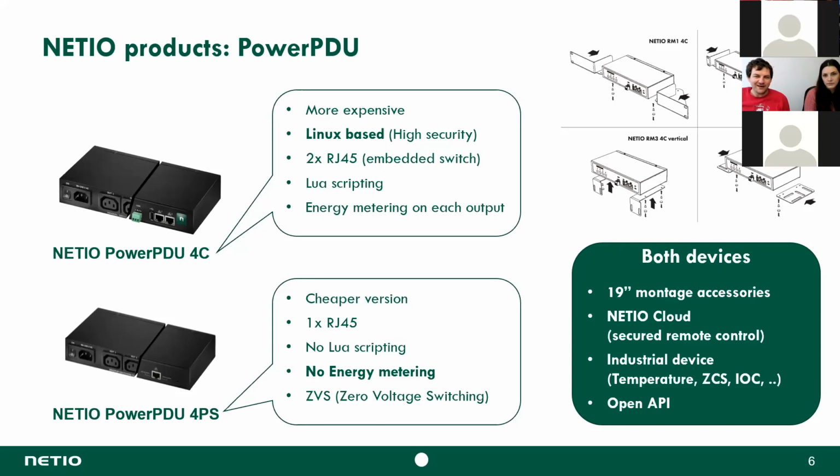By the way, Lua scripting is a typical question. What's the feature of this more expensive version? There is a serial port which can control the outputs on your own protocol because of Lua. You can define time switching in very complicated schemes. So, for example, only on Tuesday, only 10 to 11, switch something off because of something.